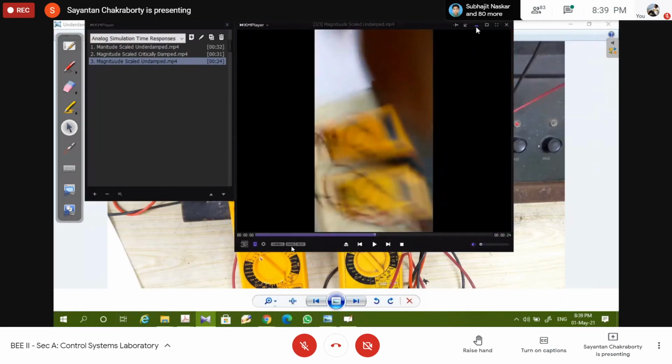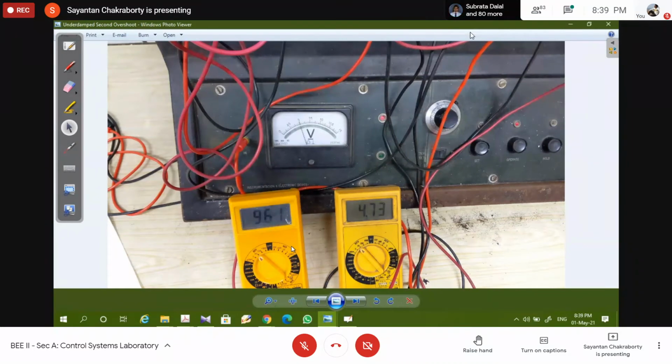Before that, do you have any query or any doubt regarding this particular experiment? The main objective was to solve a differential equation. What I have seen is that solving a differential equation is nothing like getting the expression of x(t) theoretically, but in a physical manner. We're showing the exact transition of x(t), or the time response of x(t), using this analog simulation. And that transition of time response follows the corresponding differential equation.